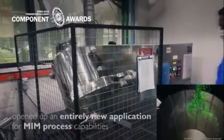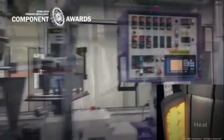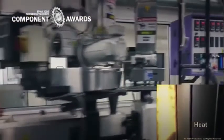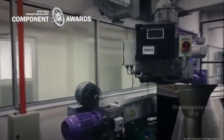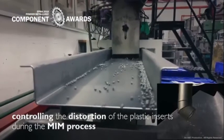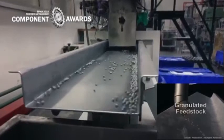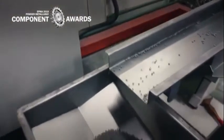This product has opened up an entirely new application for MIM process capabilities, and is definitely the most complex part created by AMT PTE Limited to date. Development efforts focused on controlling the distortion of the plastic inserts during the MIM process, as high injection pressure and temperature greatly affect the insert integrity.